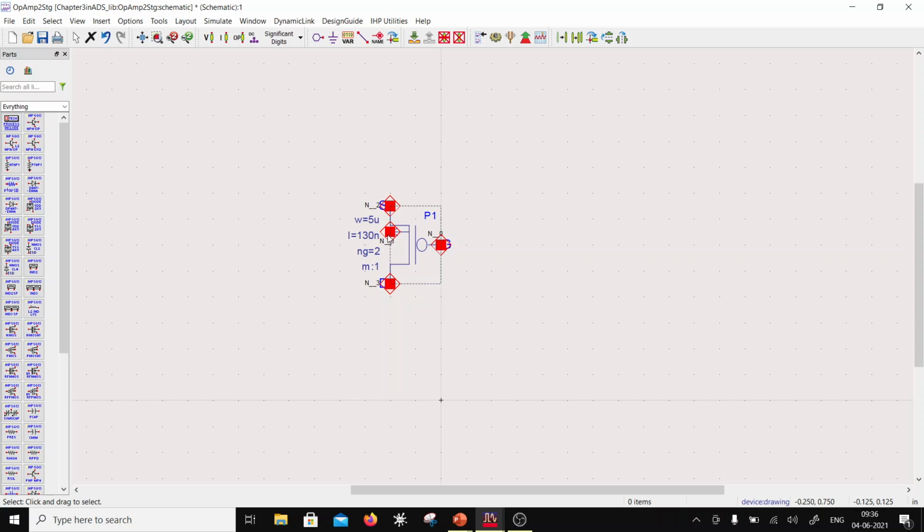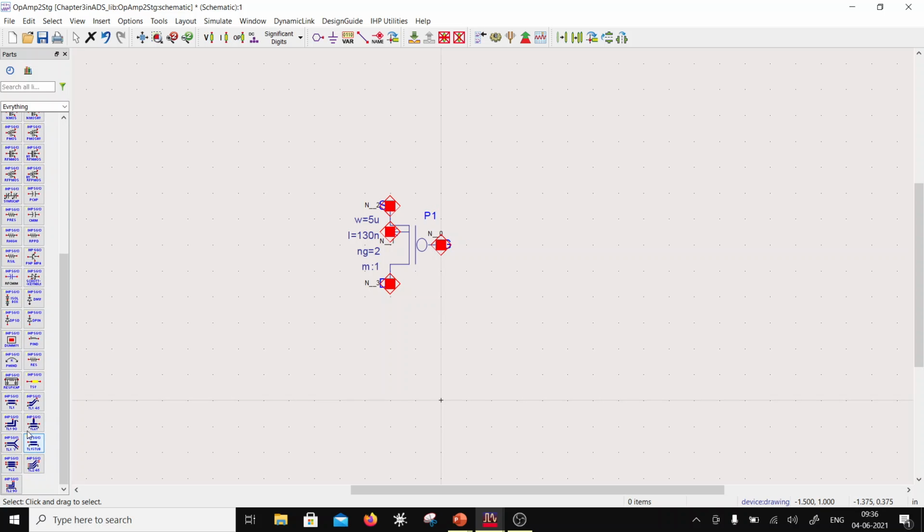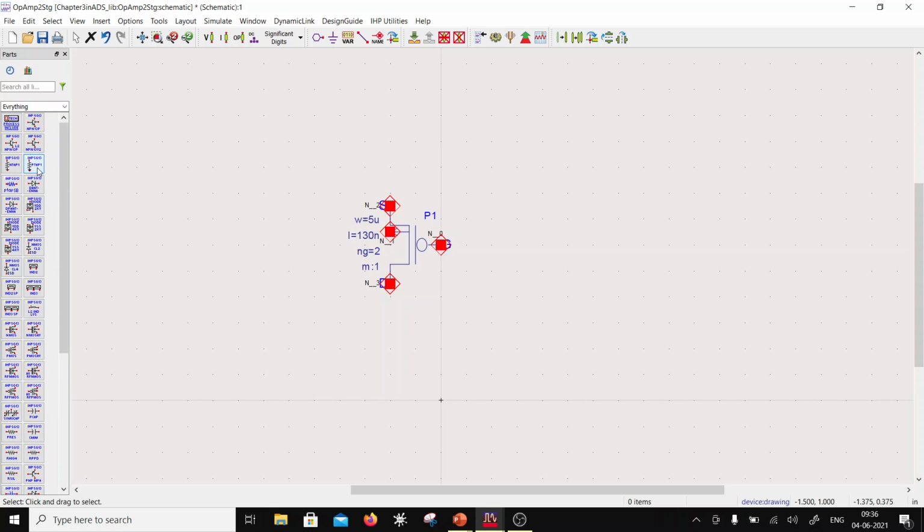Once you're done with this, you have to ground this or connect this, and for that you'd use ntap1. So let me see if there is a ptap1. So ntap1, sorry. Now this tie would go to, okay, so this well would be connecting here, and the tie would be connecting to the supply.